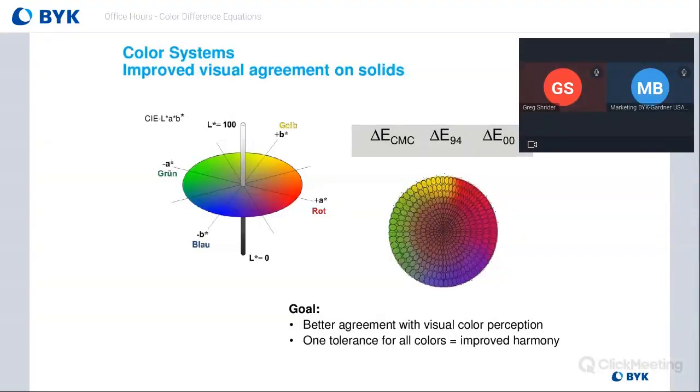If you're just looking at a textured paint product and you want to just use a color measurement device, typically a sphere instrument is going to be preferred because it's going to help to eliminate the texture as being part of the measurement. So you can look at the color difference as something that you might have to change in the formula itself. April, we can send you more information on that product as well.